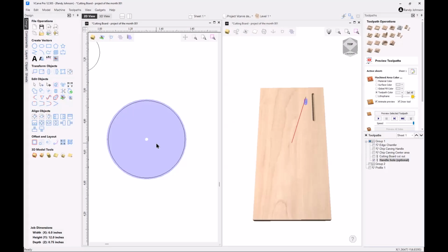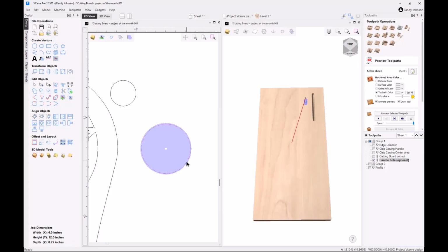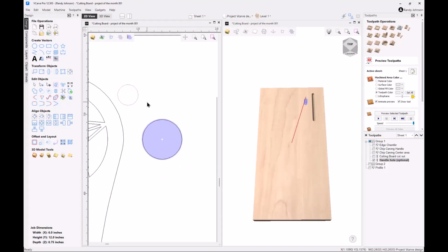So that's a great way to custom size a hole. And then it allows you to do your layout with a standard size shape of 0.5. Now, when I said earlier about this one being 0.26, we could have done the same there. I could have made it exactly 0.25 and then used that allowance offset that we just showed you there, and it would have done the same kind of thing. And then it would have fit in that area.